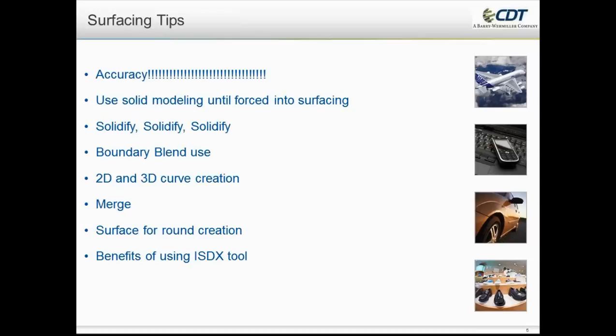You will find that a lot of the surfacing work that you do, and I was a victim of this when I did a lot of design work in my past jobs, that I would do all my models in surfacing, and my model trees, you couldn't scroll through them. They would be nothing but curves and merges and surfaces and solidifies and merges and more surfaces and more curves, and these things would be forever. If I had just sat back and looked at it, I probably could have done 25 to 30% of my features with solids, and then from that point gone into my surfacing, and it would have been much easier to deal with.